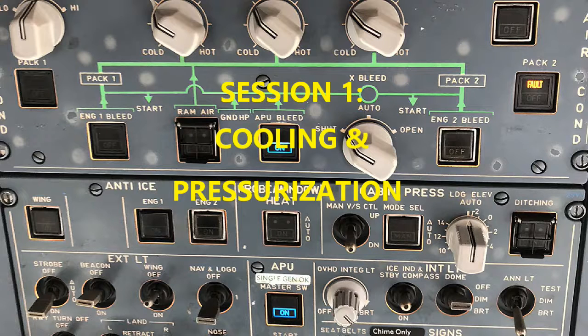So now let's go over the BITE test. There's not a whole lot to this. BITE is BITE. It's going to do its check, run automatically, and if there are indications of fault, it's going to let you know on the display. Remember, our main thing is our zone controller, because that's running the built-in test equipment function for the temperature control system. It's going to monitor both the hardware and the software, and if there are any failures, it's going to send that data to the CFDS.